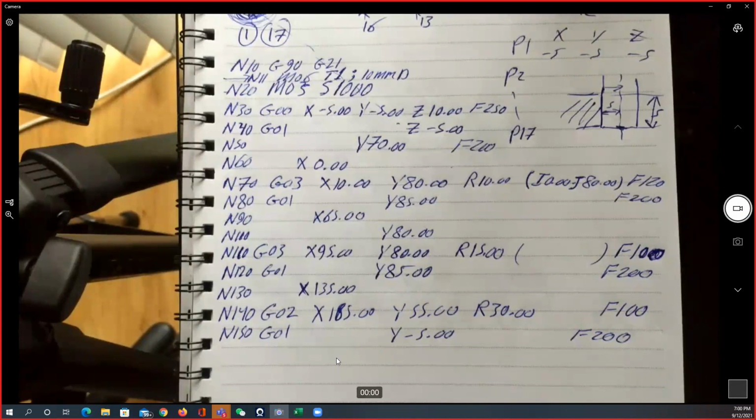Slower, you're going to increase the time. So if you multiply both, where the t is taken to the power of n, which is the slope of the multiple speeds. That means if I have a curve between the cutting speed and the tool life, it is going to be a straight line going downward. So lower speed, longer life, but the time of the machining is going to increase.